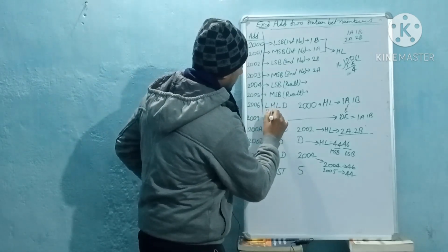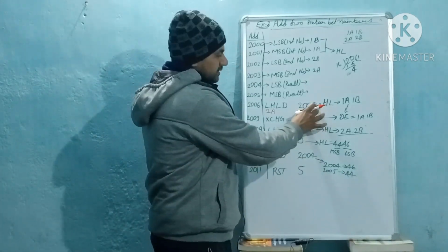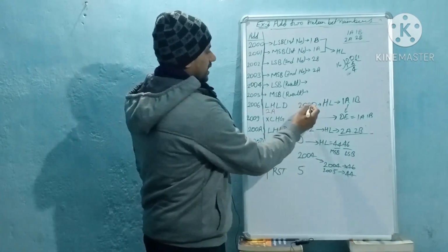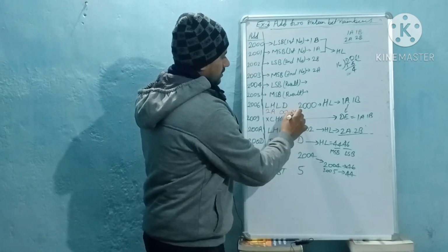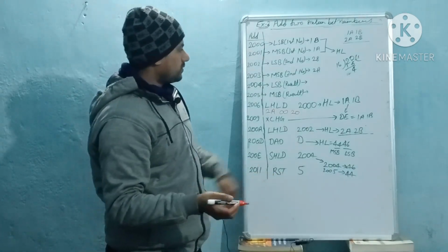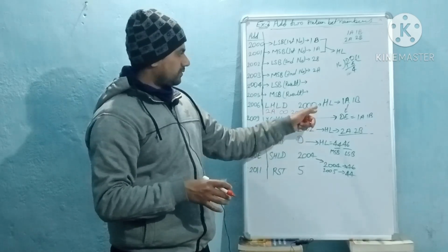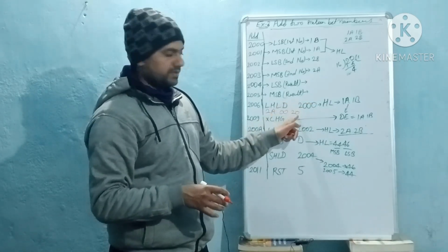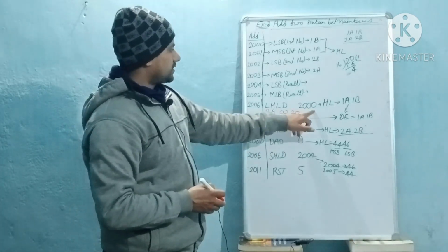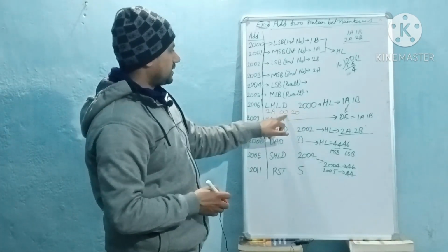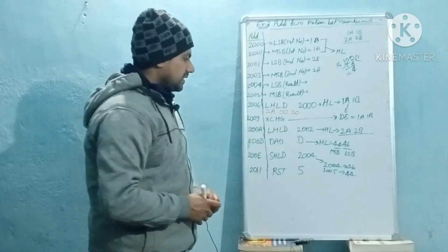And for this memory address, we have to write 0020, because I already explained earlier that we write the address in reverse, or you can say we write the LSB first and then the MSB of the address. That's why the LSB of this address I have written first, then the MSB. Then the next one is XCHG.